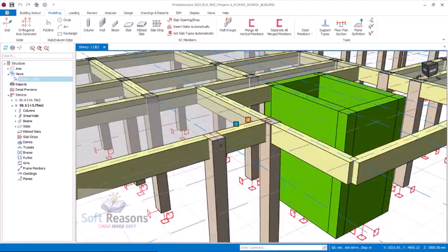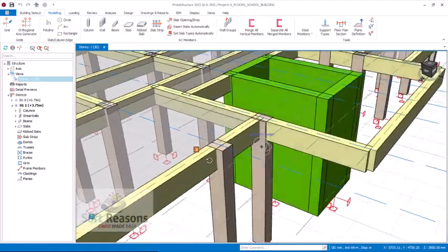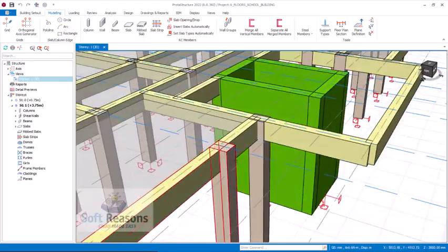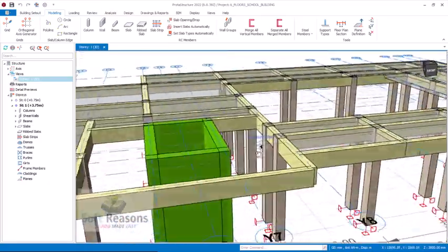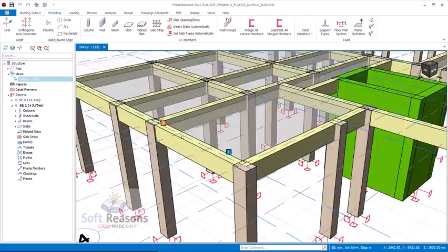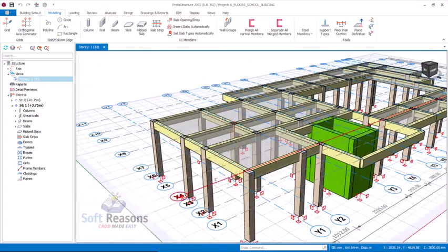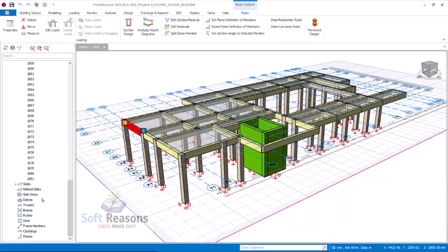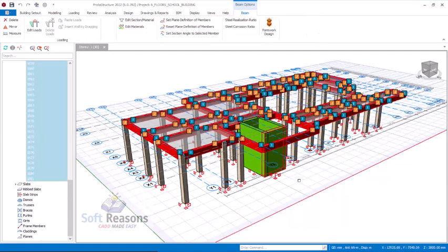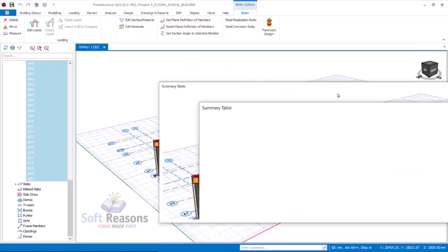Now we want to be changing this beam sections. We are using beam sections 225 right there. We change it to 300 since some of this beam is going to be carrying columns. So this particular first floor beam, we will change the sections to 300 by 500. For you to do that, you just have to come to this provision where you have your beams, select the first beam, scroll down, and then hold the shift key, select the last one to have all the beams in the building selected. Right click and then click on edit properties.